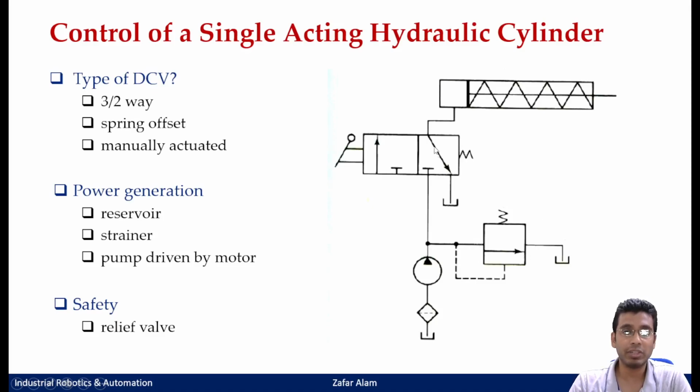That will be the case when you actuate the extension portion of your valve and your cylinder starts to extend. That means you are having a normal pressure. But suppose the cylinder reaches its extended position, and you are keeping the lever in its engaged position, and the cylinder has extended completely. Then again the pressure would start building in this line, because your cylinder cannot move any more forward and your pump is still running.